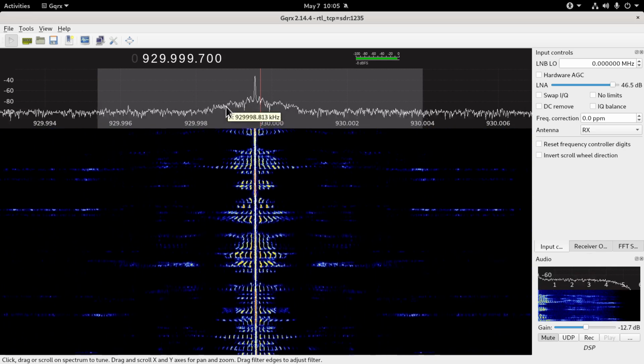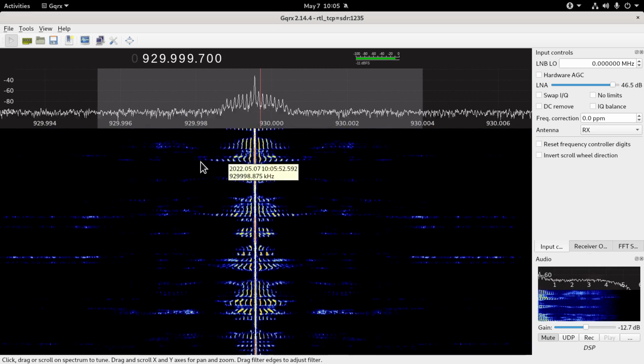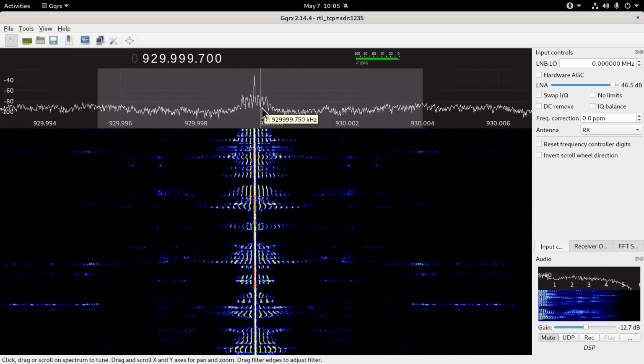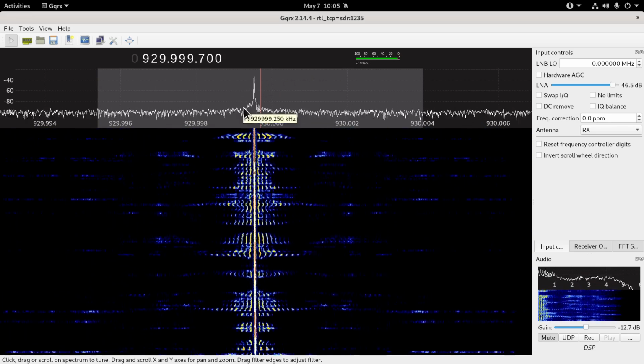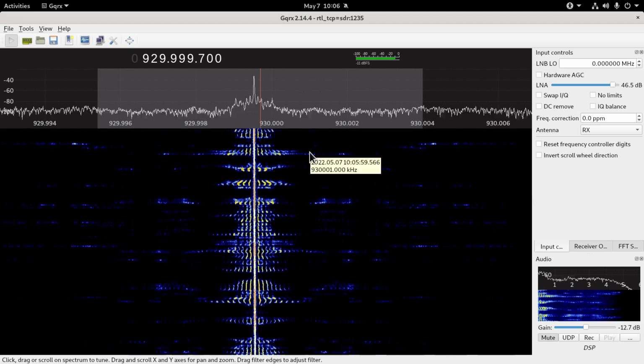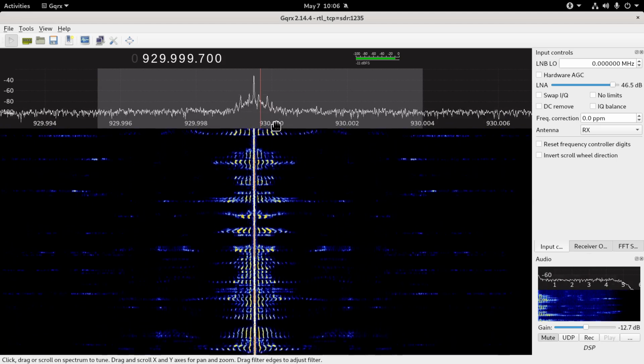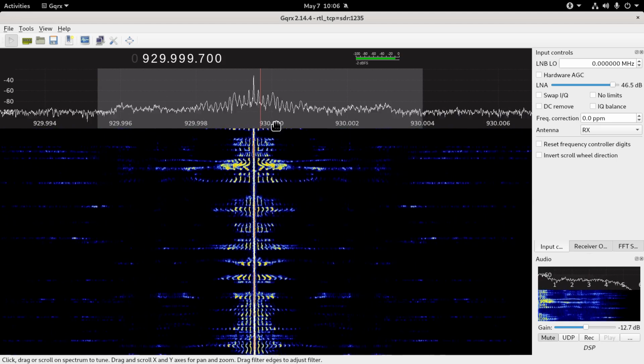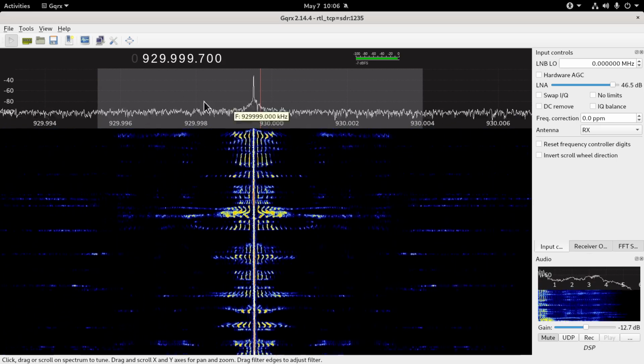Now, one doesn't contain any more information than the other. It's not like there's low frequencies here and high frequencies there. It's all here. That one's just the inverse on the lower sideband. So there's power wasted essentially that doesn't give any new information over the air. That's the carrier and one of the sidebands.